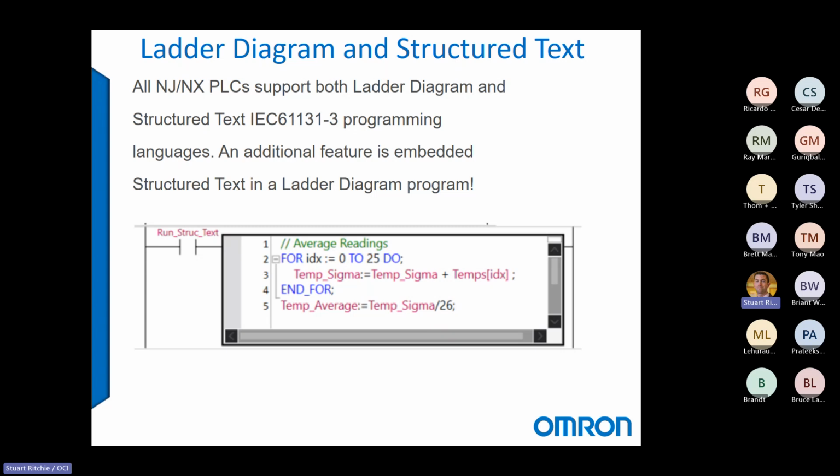Now we're going to get into some of the things that Omron may do differently than the platforms you're used to. So we support ladder diagram and structured text, or ladder logic, it's commonly called. So we follow the IEC 61131-3 programming standard quite closely.